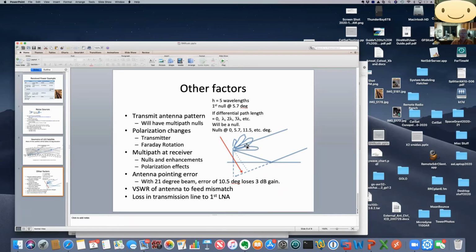And then it'll be this really, really, really deep null. And then another 6 dB enhancement, and another really deep null. So what'll happen is the satellite comes along, you work your length equations and think, oh, I have 5 dB margin. And then you actually look at the actual traces, and you'll see the signal bumped up significantly higher than the margin. And then it dove down to way below, maybe a 20 decibels deep null sometimes. So it's just a thing that happens, and you have to be prepared for times when, no matter what your length calculations say, there's going to be signal dropouts.